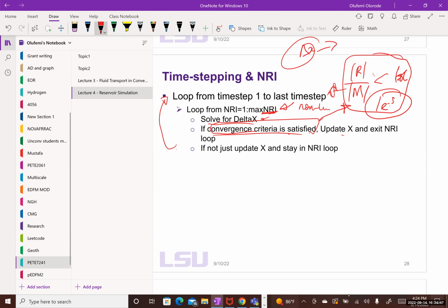Yes. The class is over. If you don't have any questions, I see you guys are packing up, but if you have questions. Yeah, what was that term, the normalization? Mass accumulation term. What should it be less than? Tolerance, 1e-5. Common value, or 1e-6. 1e-5 is a good value.